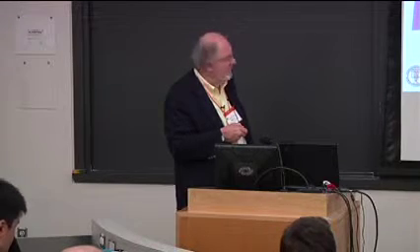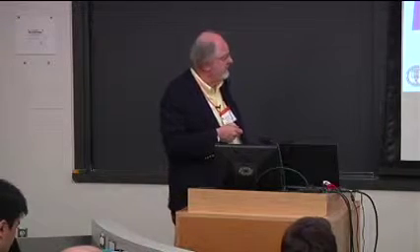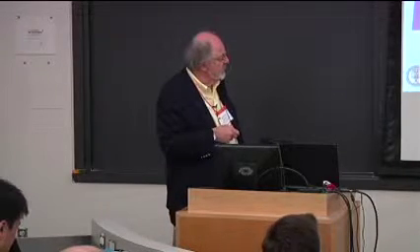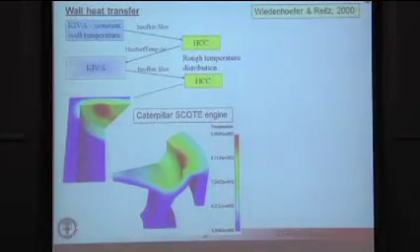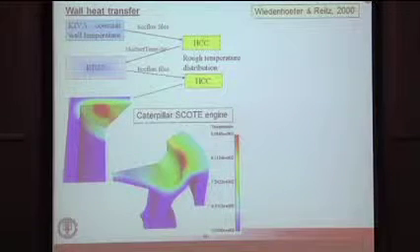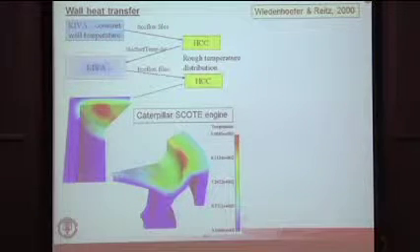head temperature. This just shows some results from Jim's thesis work for the Caterpillar engine in our labs, single-cylinder oil test engine. You can see wide variation in piston surface temperature. This red region here corresponds to alignment of one of the jets for a high load operating point, a very high temperature at that piston bowl edge.